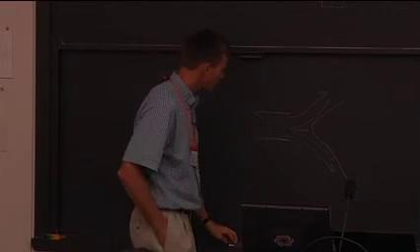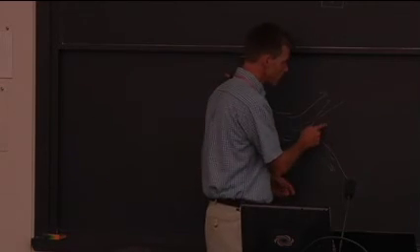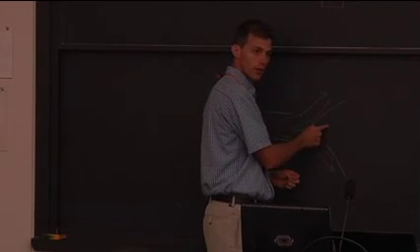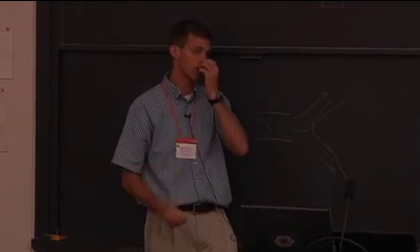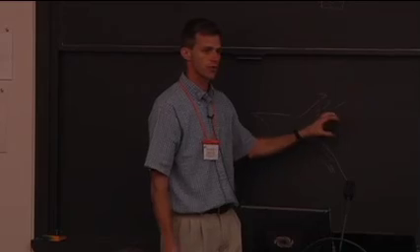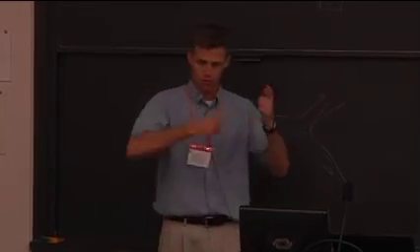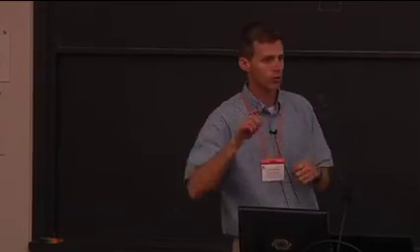And also, our friend Robert Chang would point out that if there's no flow recirculation, there's no Zeldovich. Remember, Zeldovich NOx is proportional to temperature times residence time. So you don't have this piloted region, which is just spinning around making NOx proportional to time.